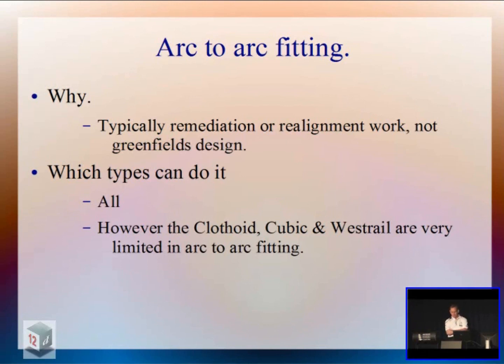And this is because there are only certain mathematical situations where you can get a curve with a radius here and a radius there at a portion along the curve that match up. And I've seen the pain personally that New South Wales railway designers go through trying to fit an arc-to-arc cubic parabola. They spend hours just jigging a little bit here, a little bit there, until they finally get a curve magically appearing. And I don't know how much the situation's improved, but it is actually very difficult.